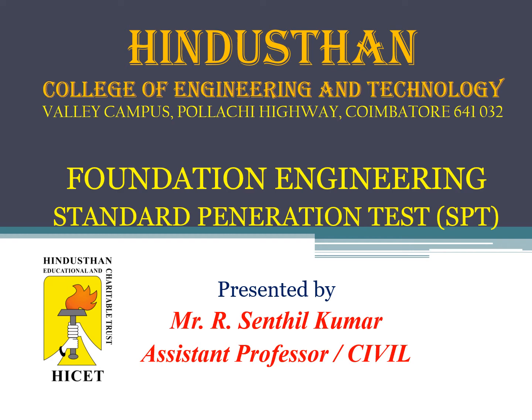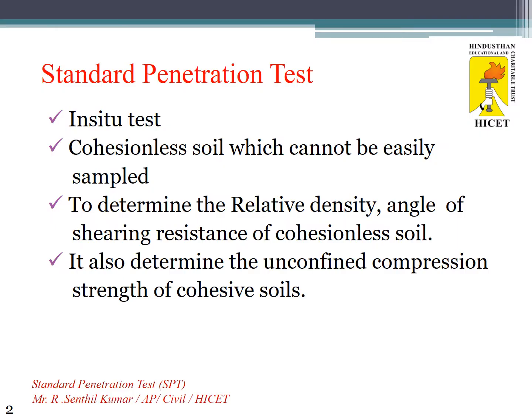In this video, we discuss the standard penetration test from foundation engineering. The standard penetration test is the most commonly used in situ test, especially for cohesionless soil, which cannot be easily sampled. This test can be extremely useful to determine the relative density and angle of shearing resistance of cohesionless soil. It can also be used to determine the unconfined compressive strength of cohesive soil.